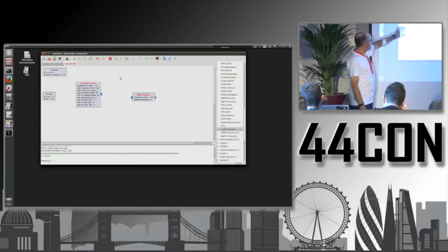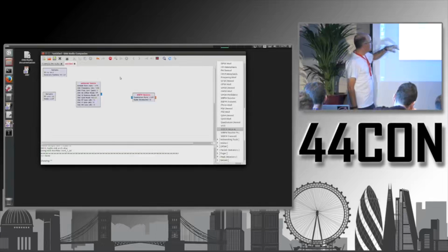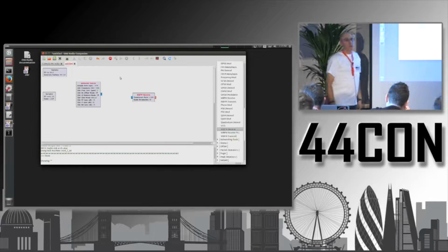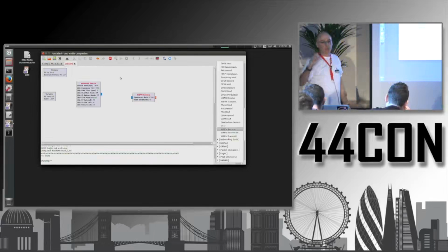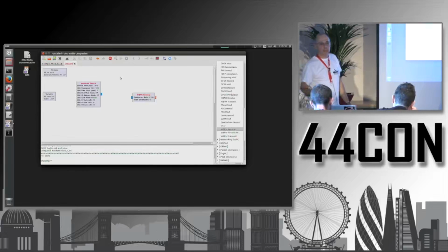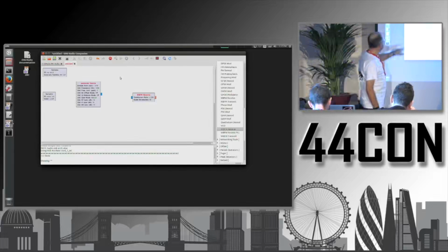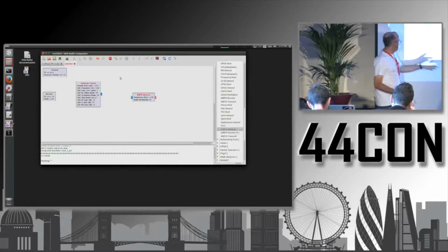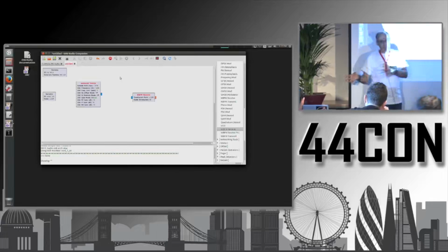And here, okay, I can work with 2 million, but since I knew beforehand that I'm going to work with that FM demodulator that does downsampling by dividing by an integer value, I just selected here the right value to end up with 48 kilohertz.